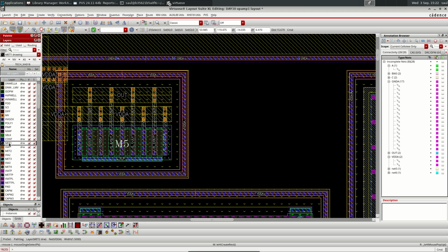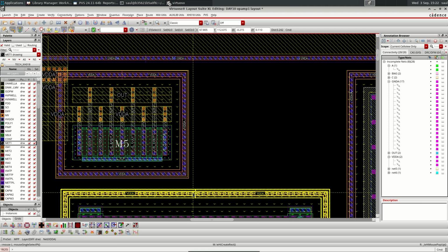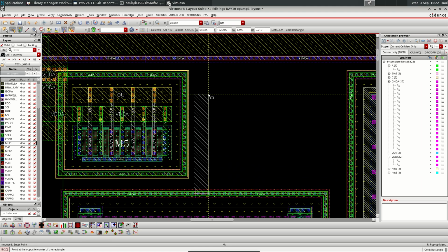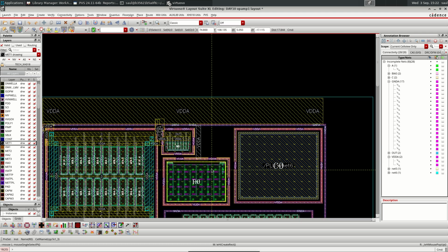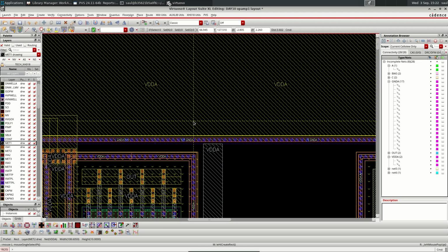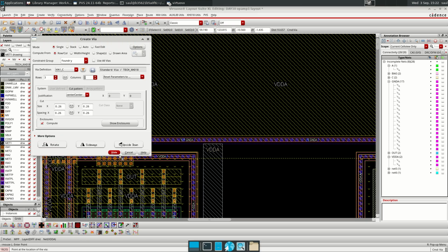The reason for that is that I don't want that activity in the transistors will propagate to the N-wells that are under the resistor and the capacitor. So I will prefer the connection directly to VDD. So in other words, this will behave like a star connection. Again, we make the connection here. Probably this should be more than enough.